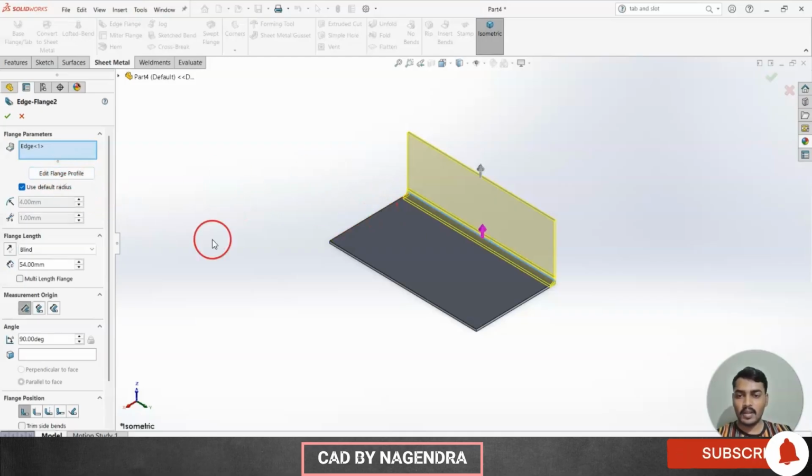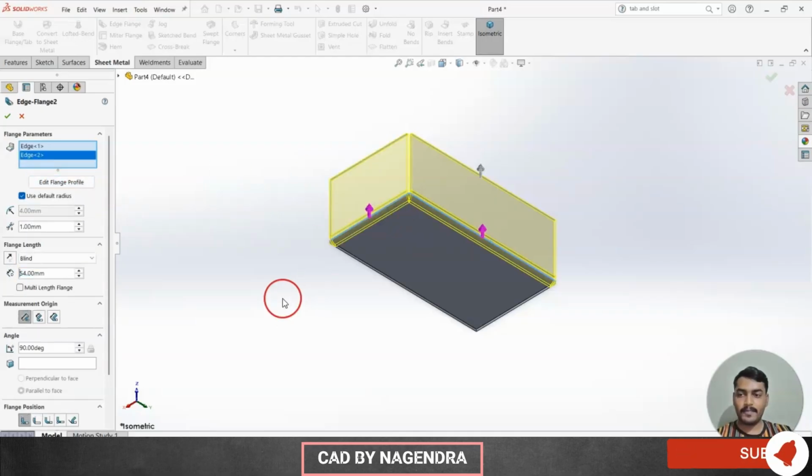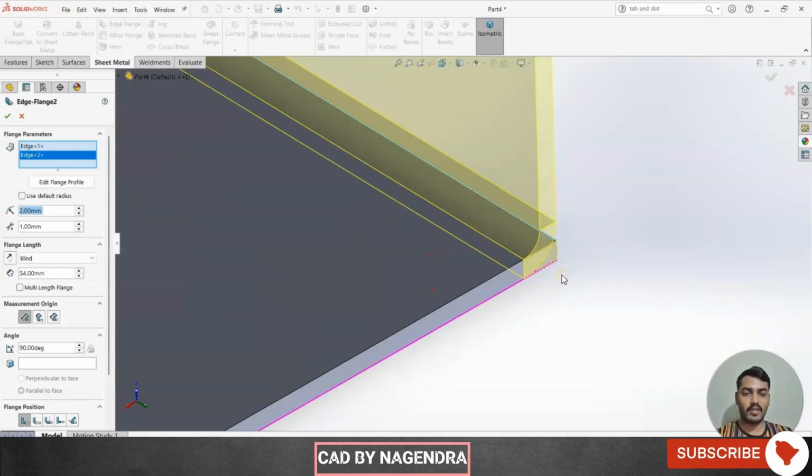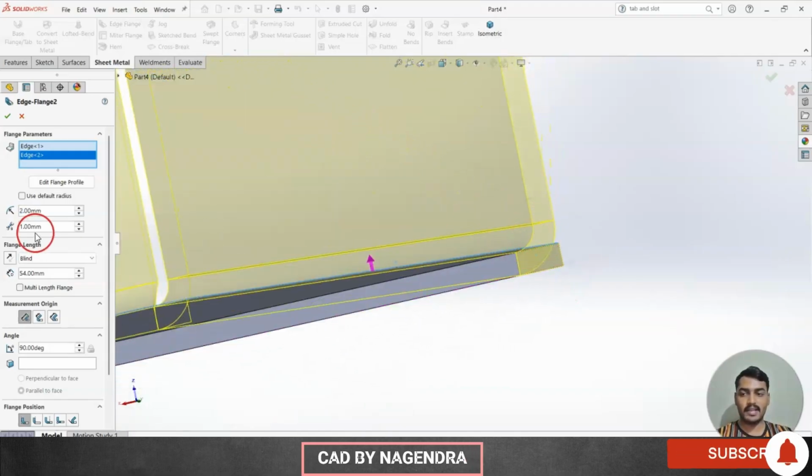For example, one more edge also I'll select here. Then next we have use default radius. Why? Because the thickness we have taken is 2 mm, so the bend radius it is taking is 4 mm. If you want to change that, just click on that and you are able to change the bend radius. This is the inner radius, and we can change it like this as much as we want.